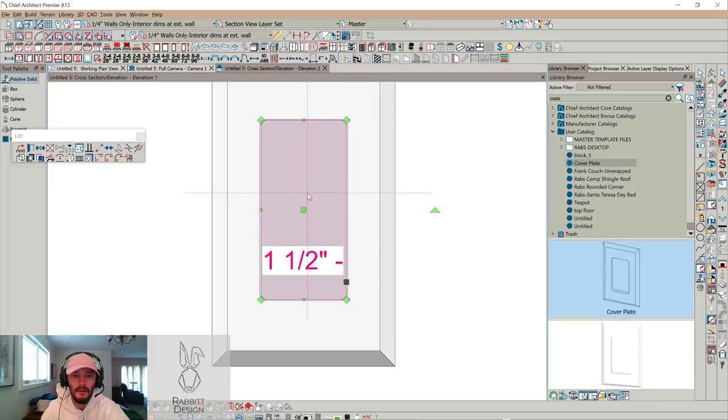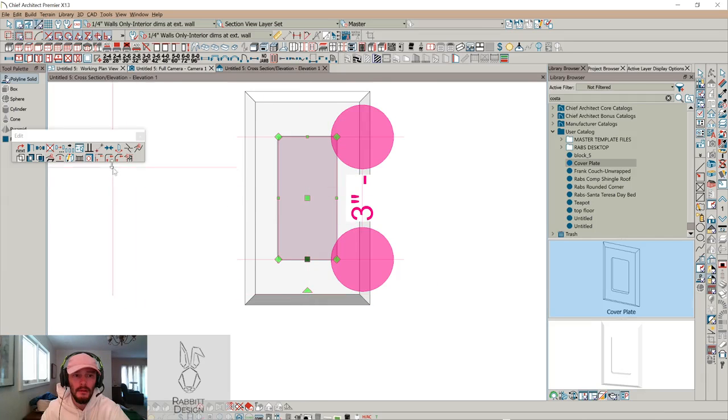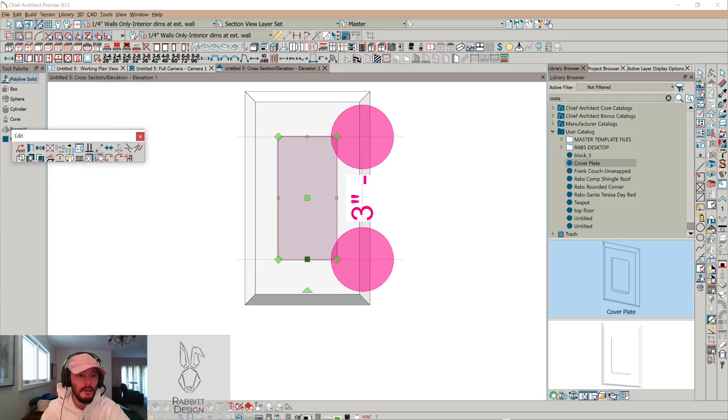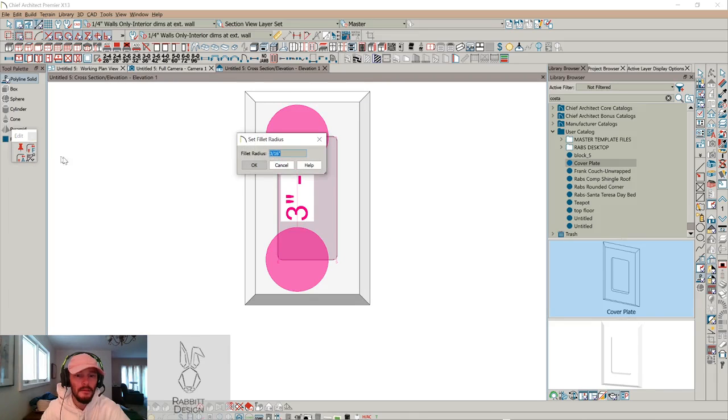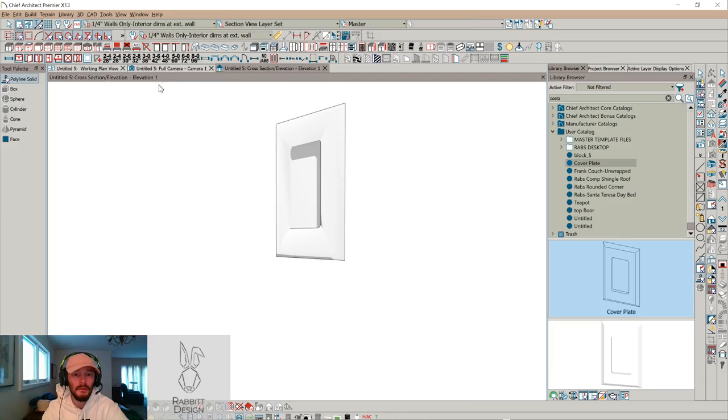What do you think? I could center this up and make this the most perfect symbol ever. Maybe I should, huh? Get that inference line there. Center it up this way. We get this inference line somewhere in here. No, it's not going to give it to me. I don't care. All right. Fillet all edges. What do we think? 1/8 of an inch. And then hit our all. Bam, perfect. Absolutely beautiful. That's beautiful.